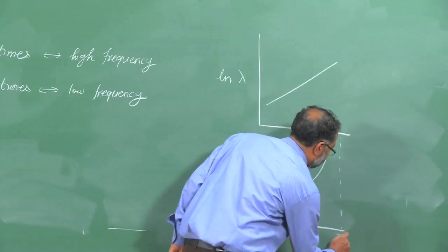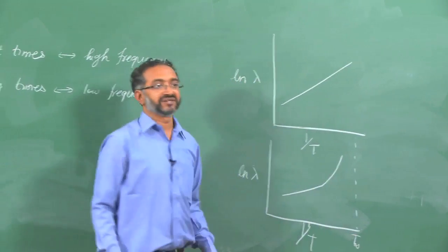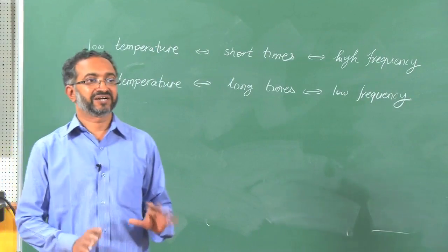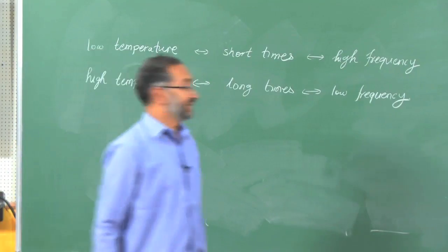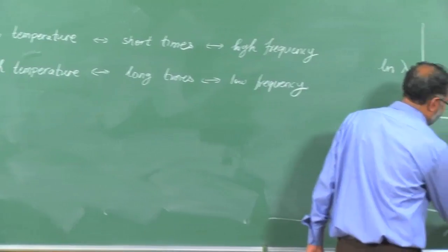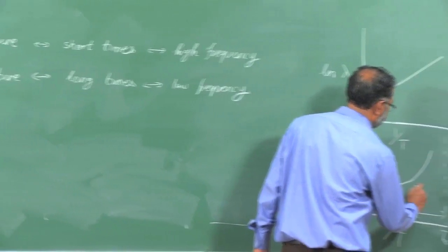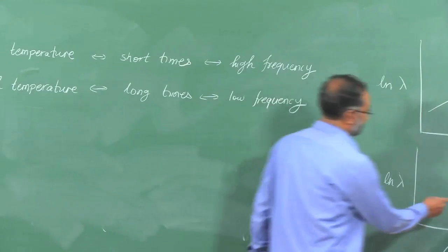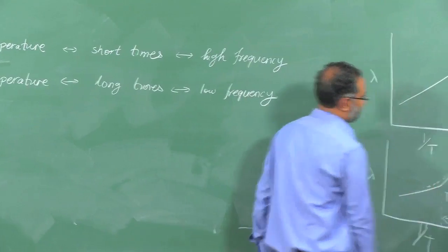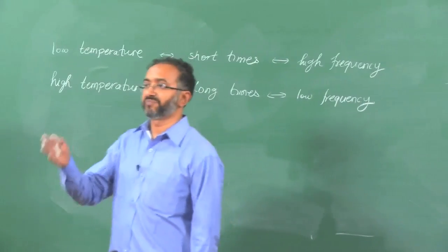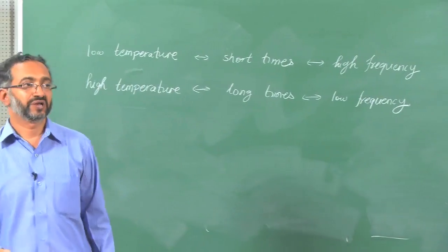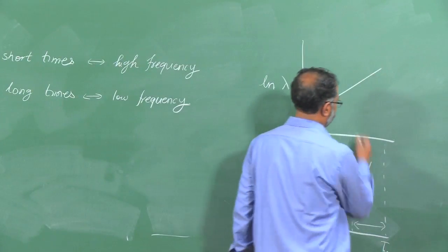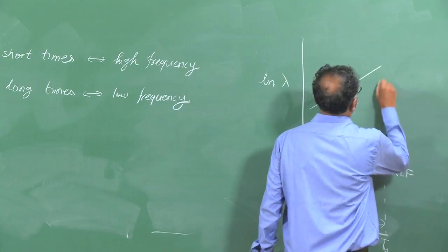And what I have plotted here is a fictitious temperature at which all motion ceases. Basically the material is practically completely frozen, and generally about 50 degrees before that there is the glass transition temperature of the material. So, near these conditions the variation is not Arrhenius. Near around glass transition for a rubbery material or a material which is close to glass, the relaxation time does not change as a function of Arrhenius. So, this is WLF and this is Arrhenius.